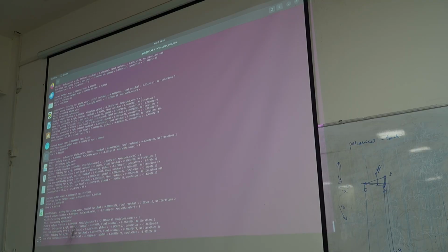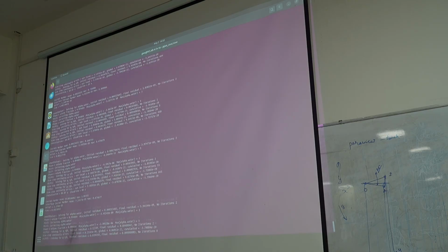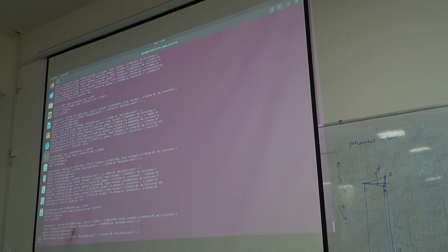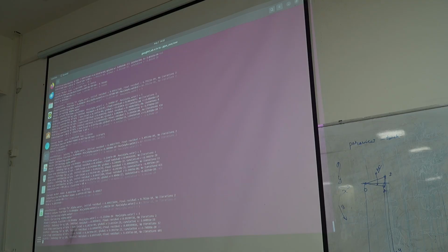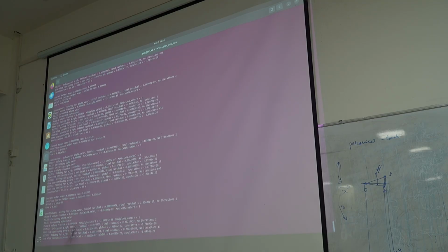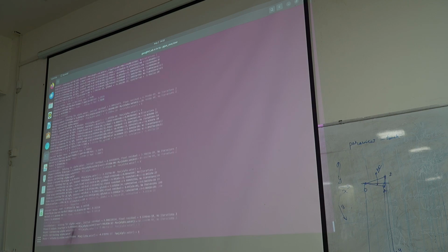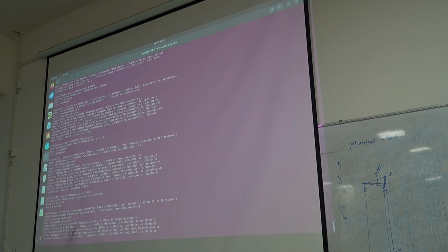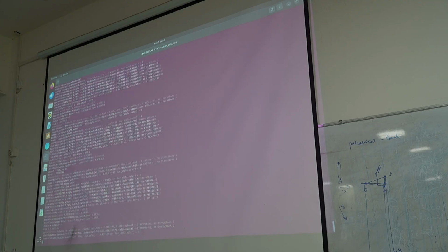So for 3D it is still workable, but for a 2D case, because the number of cells is less, adaptive mesh refinement may add additional time from redefining the mesh every time step. So instead of gaining an advantage, it can be disadvantageous in terms of computational time. So for 2D we can go with the maximum refinement.